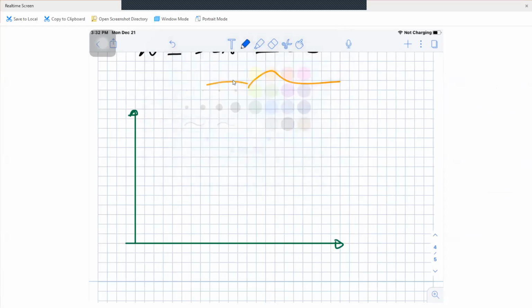Based on the requirement, here we have the following band pass filter. Look, please. We said that we have complete signal rejection, I mean the signal values will be 0 at DC. Of course, DC means 0 Hertz, and at 250 Hertz. Now, what will be the peak? A narrow passband centered at 125 Hertz. So this will be the point of 125 Hertz.